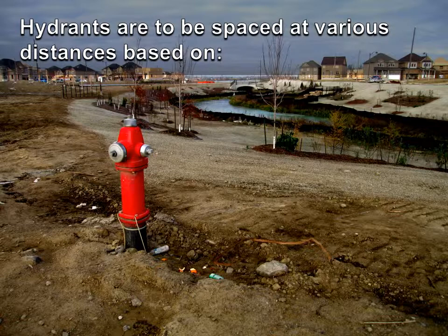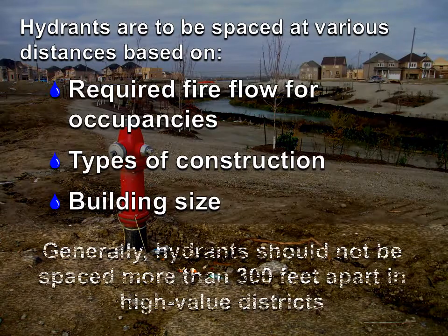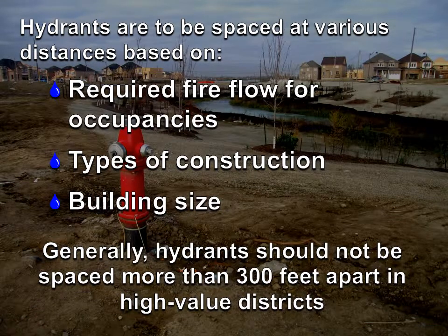Fire hydrants. Hydrants are located at intervals along water distribution systems. Hydrants are to be spaced at various distances based on required fire flow for occupancy, types of construction, and building size. Generally, hydrants shall not be spaced more than 300 feet apart in high-value districts.